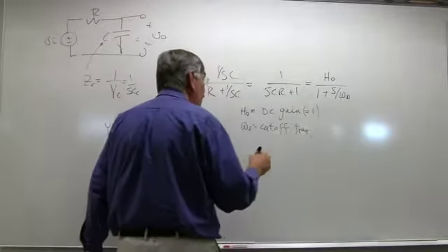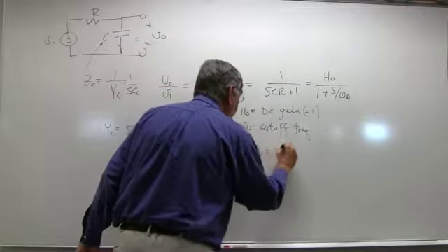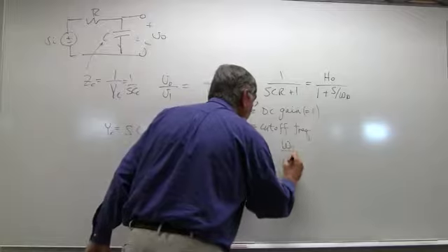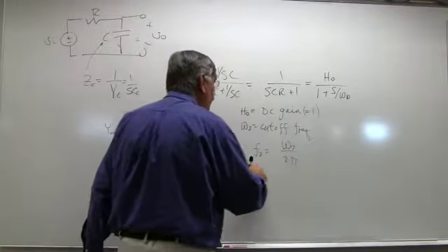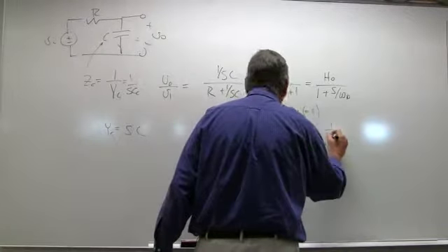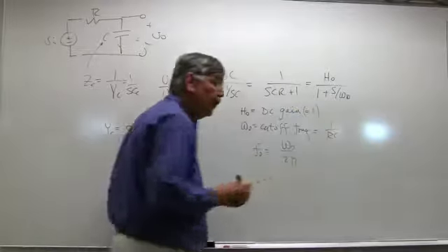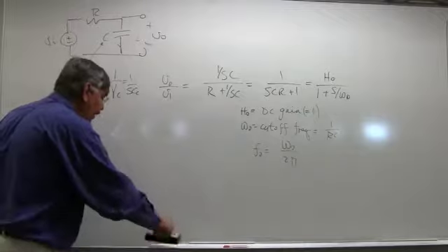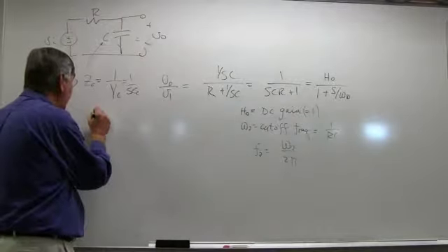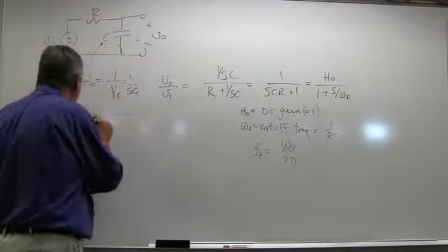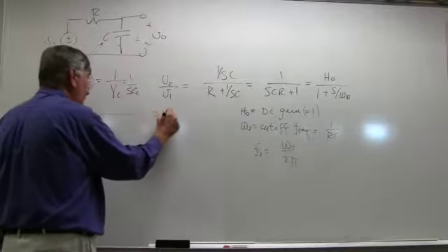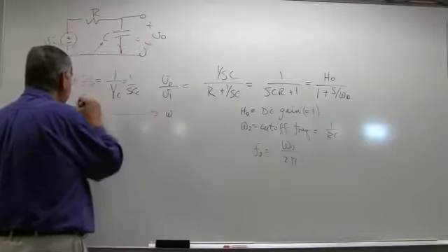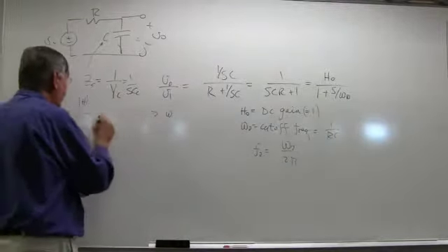This is the radian frequency. So there's an F0, which is omega naught over 2 pi. So this would be in hertz. And the cutoff frequency in this case, omega naught, is just 1 over RC. All right? And based on what we've seen before, we can make an asymptotic Bode plot of this, a log-log plot. So this is log frequency, and this is just magnitude of this transfer function.